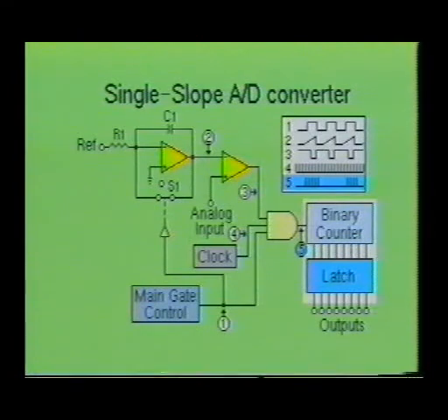The fifth and final section is the output encoder circuit. As you can see, the circuit being illustrated uses an 8-bit serial in, parallel out binary counter and a parallel in, parallel out shift register latch. The binary counter will see a pulse train of digital pulses with a length proportional to the amplitude of the analog input voltage. The maximum count of the encoder stage should be proportional to the maximum range of the analog input signal. Now let's examine the operation of this simple circuit.